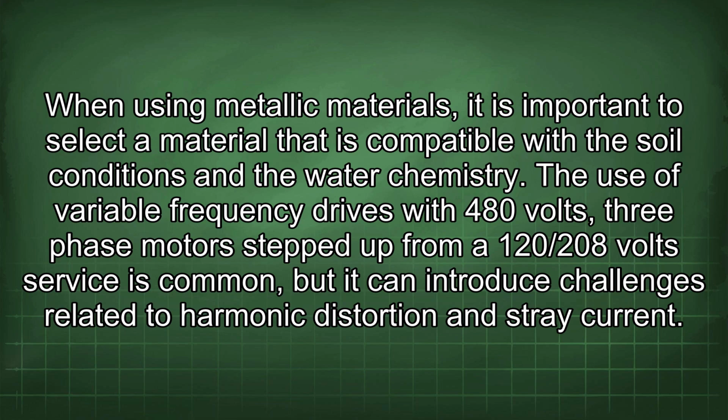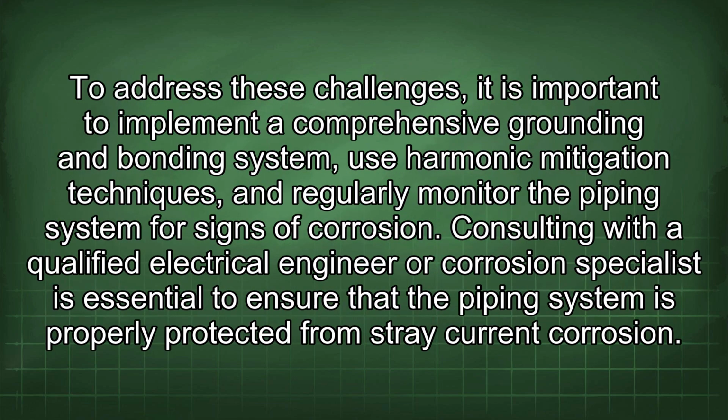The use of variable frequency drives with 480 volt, three-phase motors set up from a 120/208 volt service is common, but it can introduce challenges related to harmonic distortion and stray current. To address these challenges, it is important to implement a comprehensive grounding and bonding system, use harmonic mitigation techniques, and regularly monitor the piping system for signs of corrosion.